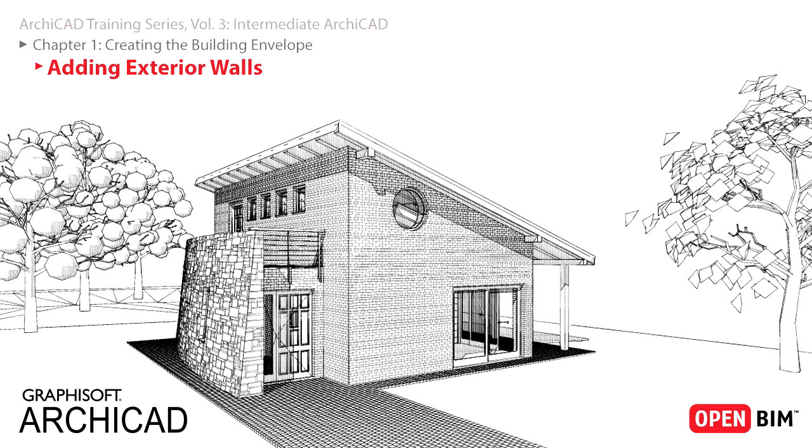Walls can have multiple skins representing the real structure, including the load-bearing structures, insulation, and finishing. Out of the box, ArchiCAD contains a set of fills and composites, but now we will create our own composite structure representing the exterior wall of the building. The necessary skin order from outside to inside is 10 cm white brick finish, 10 cm rigid insulation, 25 cm masonry block, 2 cm plaster.